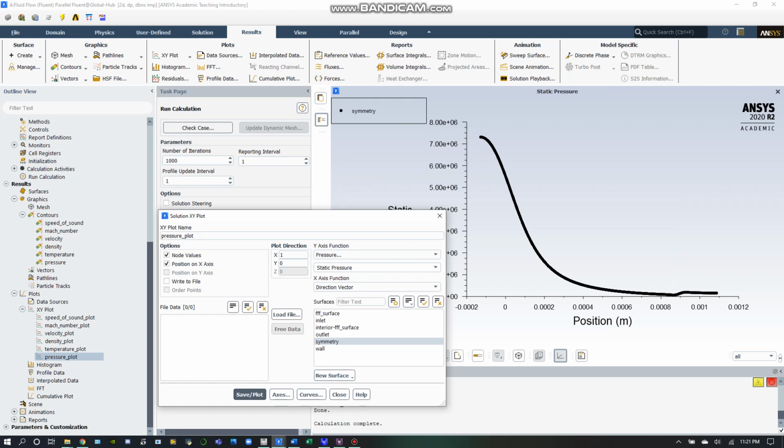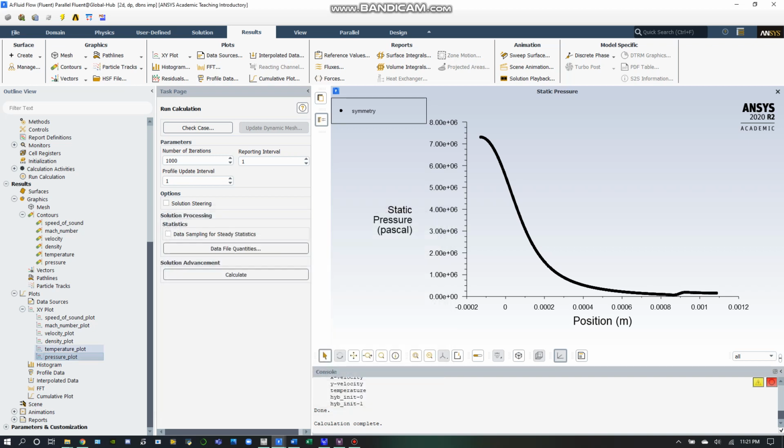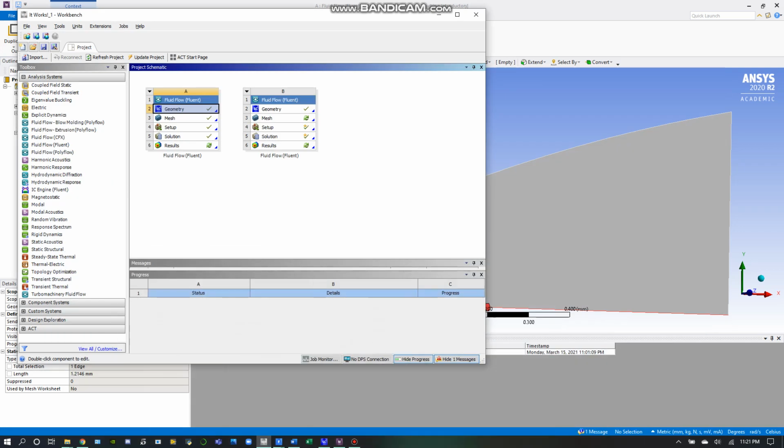Here's my data. In my report, I imported this data by using the write to file function and imported that into Excel, where I combined the data between my bell nozzle and my conical nozzle and overlaid the data and created those curves. So here are all those curves. I will repeat this once again for my conical nozzle, because there is a little bit of difference.